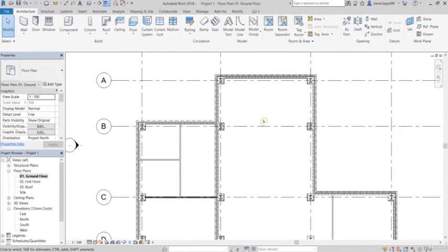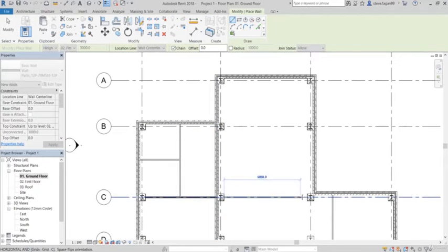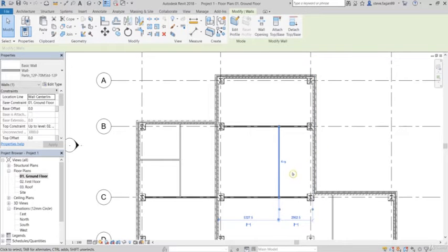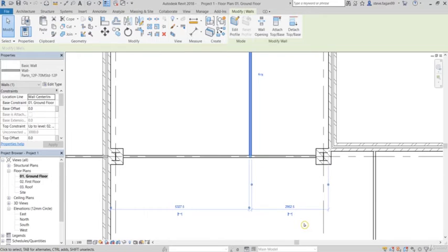So next I want to do this nice curved wall here. To do that, I'm just going to, again, roughly draw in the walls where I think they belong. And there's another one there. So draw on those nice straight walls. Afterwards, we can add in those curves. The first thing is the distance between the vertical partition and the external wall. You can see there it's set to 2800. So come down to my temporary dimensions, change that to 2800.